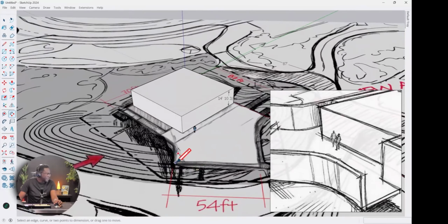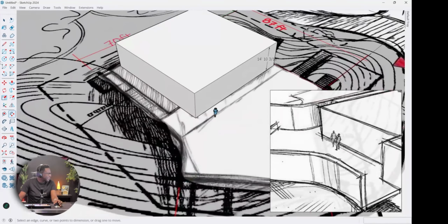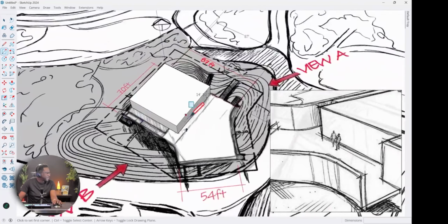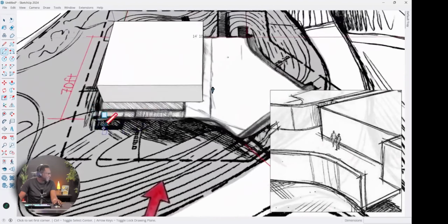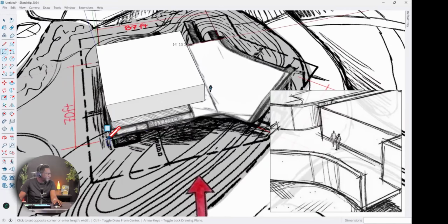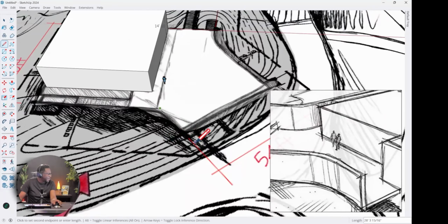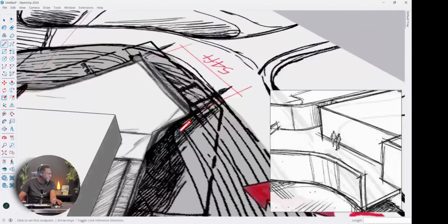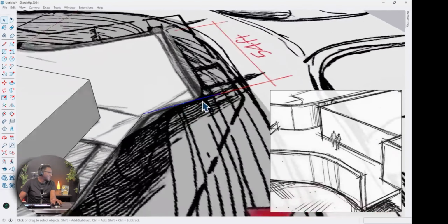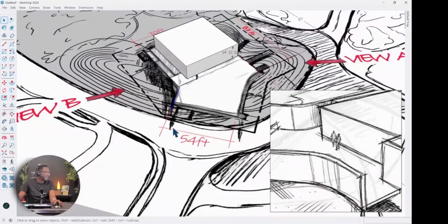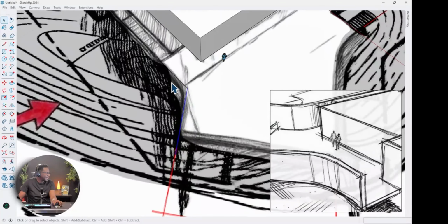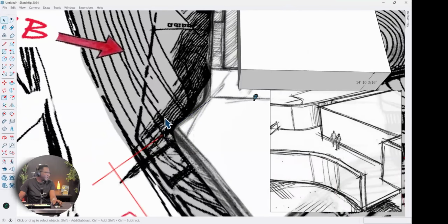All right. So now let's put in this wall that's going to be here. What I would do to put this wall in is draw it rough first. So I would use my line tool and I would do this, and then I would do this. So you can see that I have my line right here. Now, I don't know what this angle is actually, but I'm going to leave that line, and I'm going to use my rotate tool here.